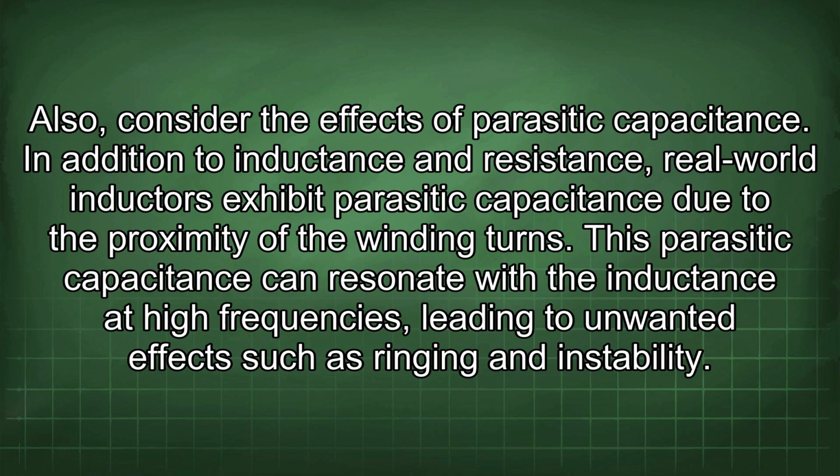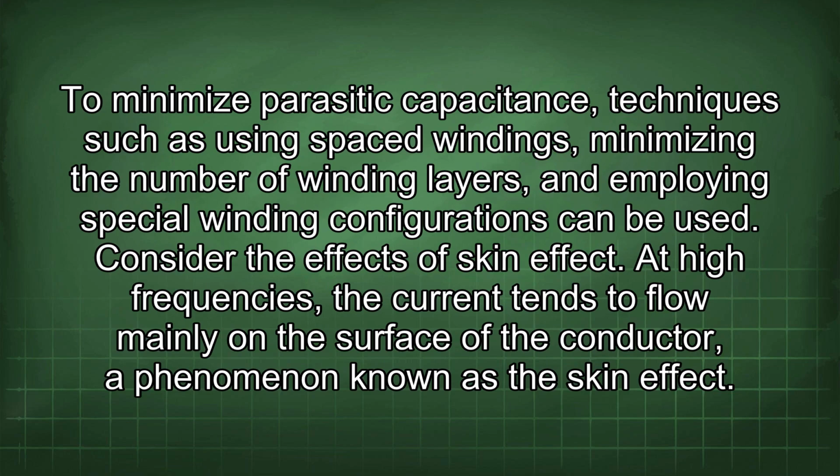In addition to inductance and resistance, real-world inductors exhibit parasitic capacitance due to the proximity of the winding turns. This parasitic capacitance can resonate with the inductance at high frequencies, leading to unwanted effects such as ringing and instability. To minimize parasitic capacitance, techniques such as using spaced windings, minimizing the number of winding layers, and employing special winding configurations can be used. Consider the effects of skin effect.